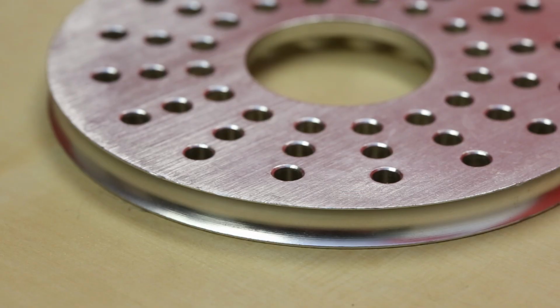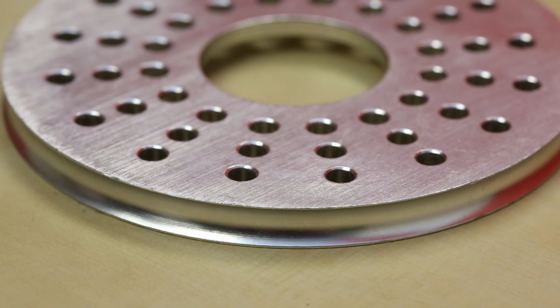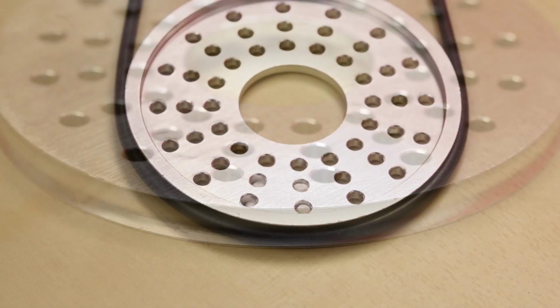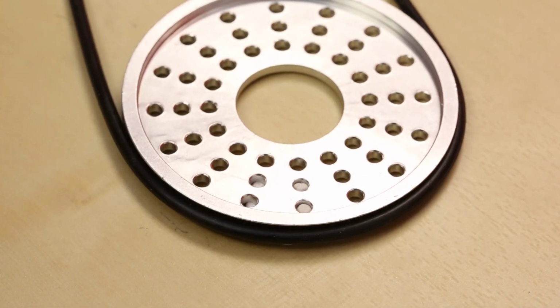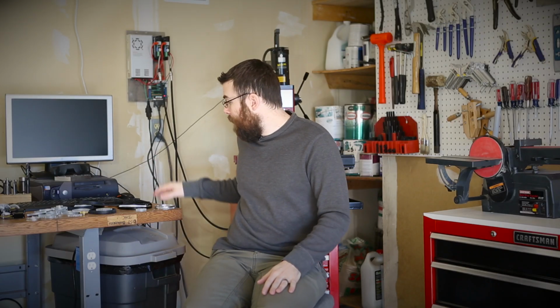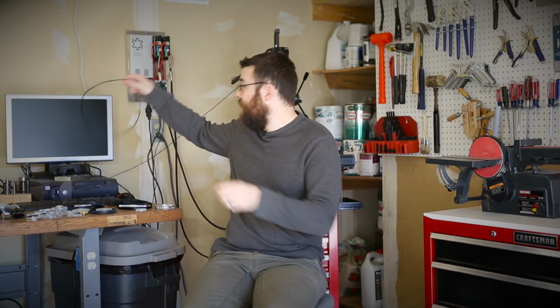The last method that we're going to talk about are pulleys. Pulleys are very similar to sprockets, except they don't have any teeth and rather rely on this smooth channel and rubber belts to transfer the motion. One of the disadvantages to using a pulley over a chain is because there aren't any teeth, you can get a lot of slippage and there is some flexibility in the actual belt itself. So you see there's a bit of flex in this.